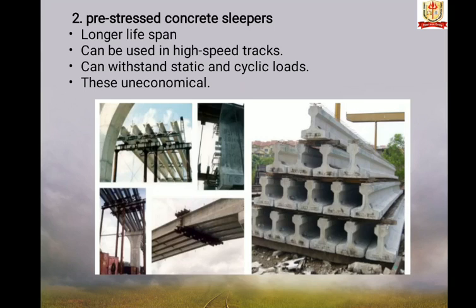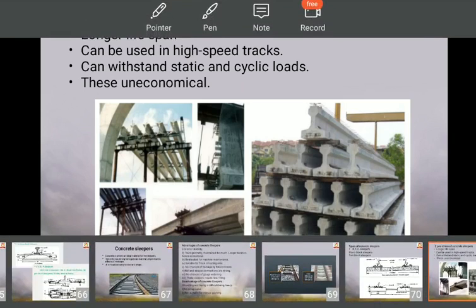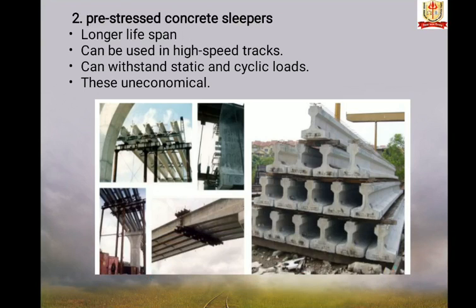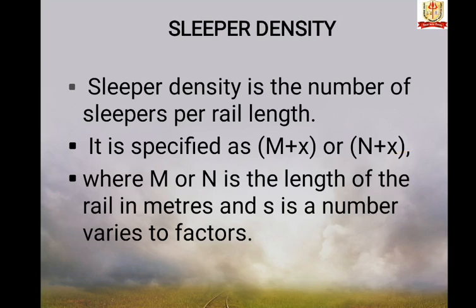But these sleepers are heavily damaged in case of derailment or accidents of trains. These sleepers have a longer life span, can be used on high speed tracks, and can withstand static and cyclic load. They are uneconomical. These are the advantages and disadvantages of pre-stressed concrete sleepers.